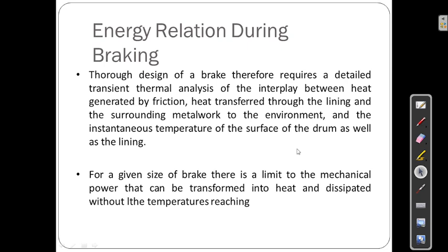This we know already. The design of a brake therefore requires a detailed transient thermal analysis of the interplay between heat generated by friction and heat transferred through the lining and the surrounding metal to the environment, and the instantaneous temperature of the surface of the drum as well as the lining. Then we will get that energy relation.